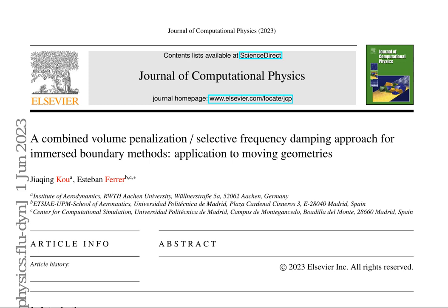In the realm of fluid dynamics, high-order methods such as flux reconstruction (FR) and discontinuous Galerkin (DG) have garnered significant attention due to their enhanced accuracy and reduced dissipation and dispersion errors at low to medium wave numbers. However, a major challenge associated with these methods is the necessity for high-order curved grids near body-fitted boundaries, which can complicate the process of generating the mesh.